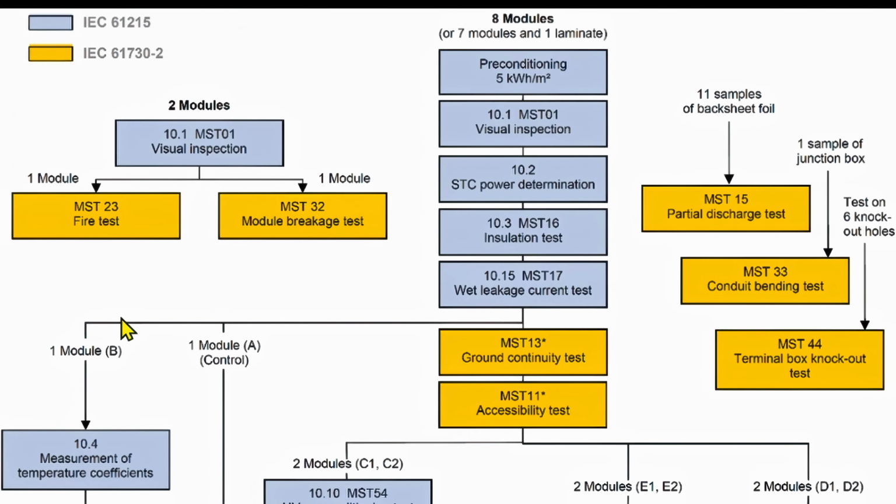Then the module tests are getting separated. So that you put one module, call it outdoor test. You put it here, on the roof, and you measure the temperature coefficient. So you measure the temperatures and take a look at the current. At the same time, you have to monitor the irradiance and especially the voltage. How much is the voltage loss during a temperature increase?